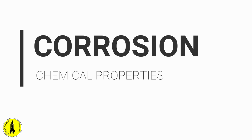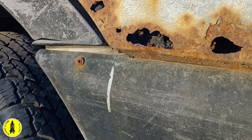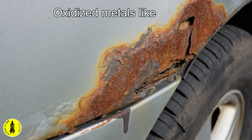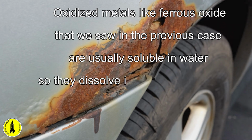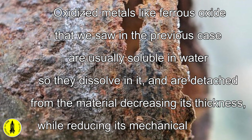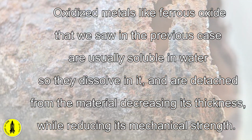Corrosion. The most widespread cases of corrosion are caused by the joint action of oxidation and water or humidity in the environment. Oxidized metals like ferrous oxide that we saw in the previous case are usually soluble in water, so they dissolve in it, and are detached from the material, decreasing its thickness while reducing its mechanical strength.